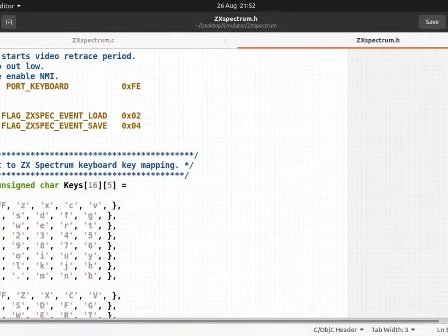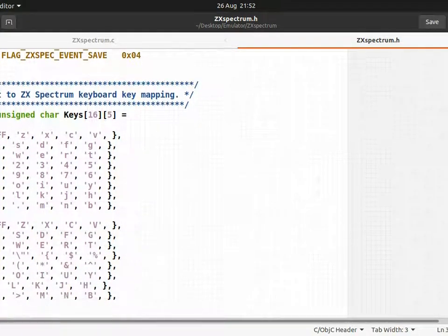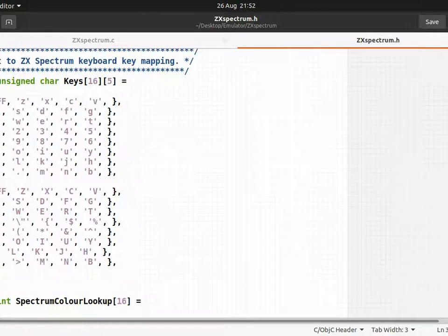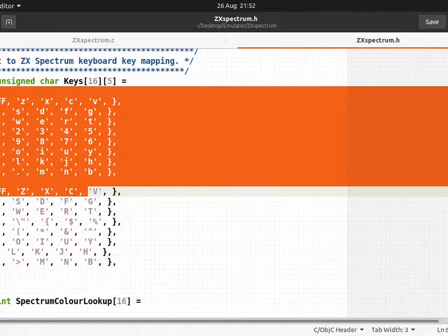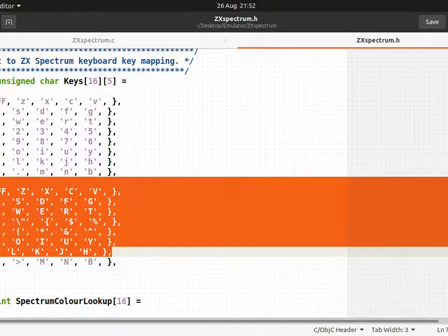So here's the keyboard layout, unshifted keys and shifted keys. I'm mapping these keys off of my keyboard onto the keyboard matrix, so that when I get an input call from the CPU, I can look up what my key press was to what the actual matrix value should be, and I return that matrix value. This is actually the same for all the ZX81, ZX80 and the Sinclair Spectrum. I haven't changed this. It uses the same matrix basically for all three of those machines.